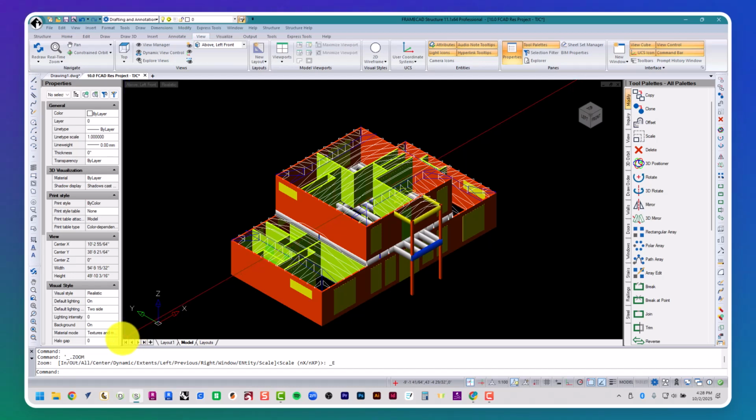When using FrameCAD Structure to design buildings, we typically sketch these ideas out and hammer out all of the details of the building, including loading, code, earthquake, wind, shape, direction of trusses or joists, bearing, non-load bearing, placement, openings.